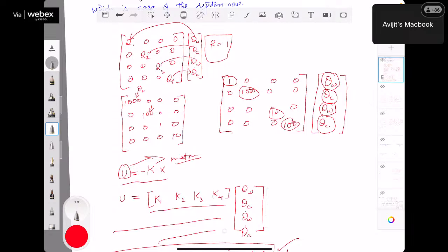But in an LQR controller, we can directly tune the Q matrix, which tells the system that this is the state dearest to me, and get me a new K matrix, which will only change the behavior of the system focusing on that state only. So here you can individually tune the K matrix by individually intervening in the values of the Q matrix.